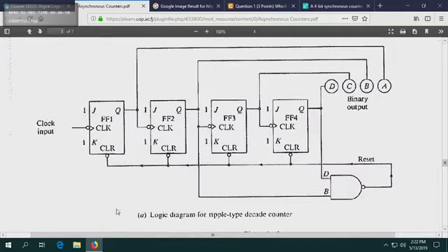Okay. Guys, now, I want you to work out for me what is the scenario here. I give you a small exercise. We won't have a very long lecture. We'll finish very shortly. I want you to work out what is the scenario in this particular diagram. What number is it counting till? Remember the word mod. If it's mod 12, it counts till number 11, and then after that resets.